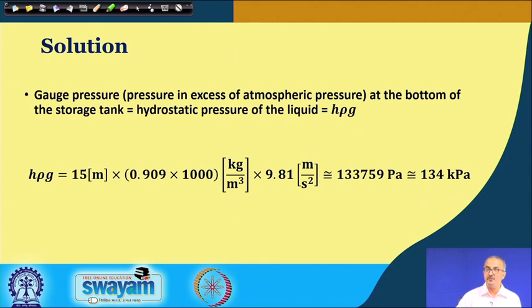So, be careful whenever you are reading the pressure, whether the pressure has been given in terms of absolute pressure or gauge pressure. Many times we make mistakes by not converting the gauge pressure into the absolute pressure.